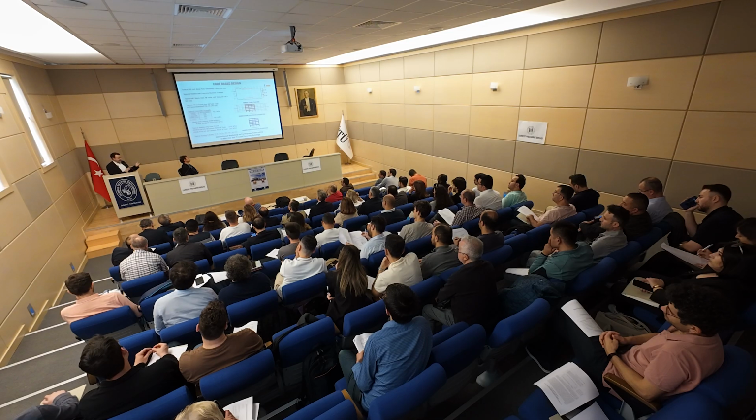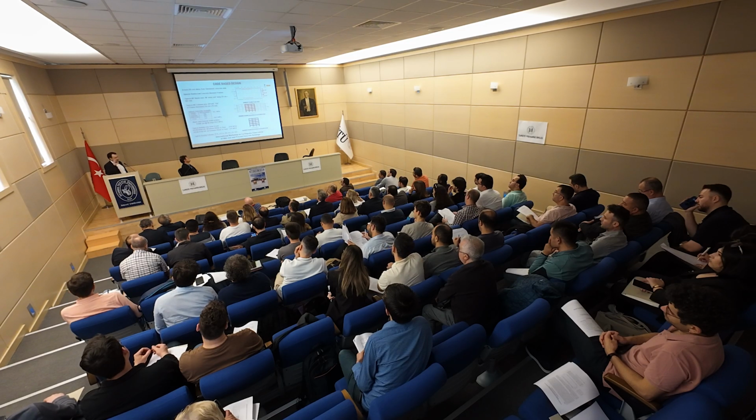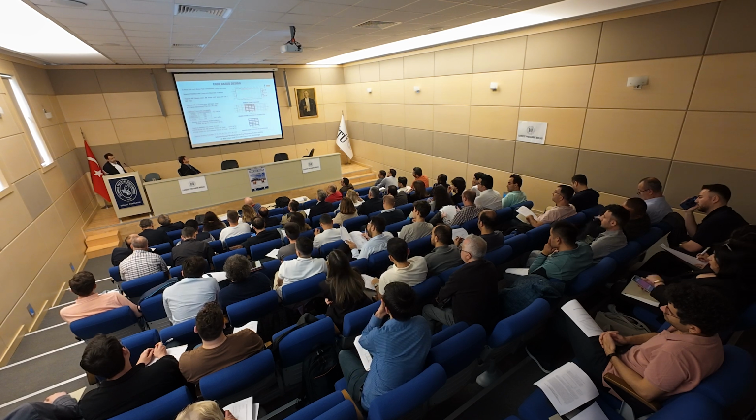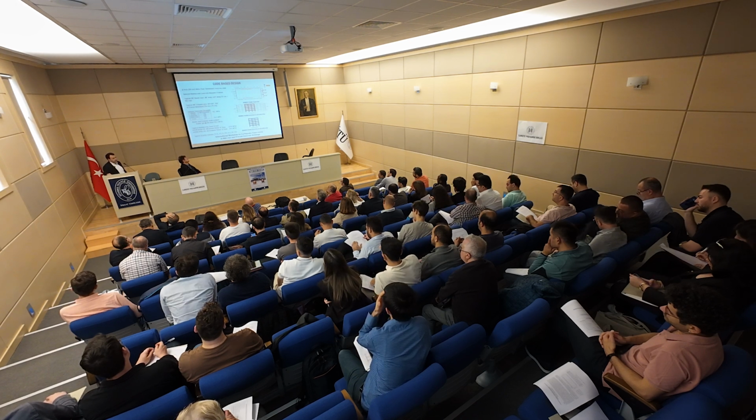Here, just because we also wanted to be consistent with the definition, the second bullet point there, a special reinforced concrete moment frame. By code, the R factor is 8. We're using a ductility factor, but it's not by chance that I use the same R factor. So I used that value as a reference. But you could use another and then check with your nonlinear time history analysis.